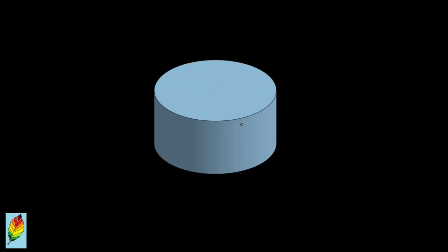An example of revolve that adds material is taking the same square as before. This time, however, instead of using the center of the sketch, we use this edge of the sketch. The entire sketch then revolves all around this edge to form this cylinder.